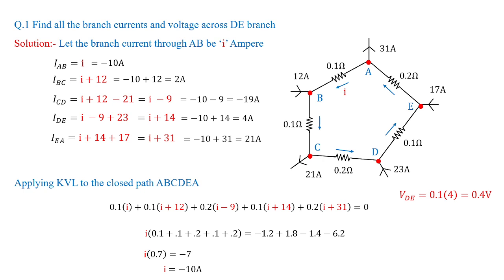In order to cross-check our result, you just apply KVL in the anti-clockwise direction and you have to get the sum of the voltages equivalent to 0. You can comment in the chat box whether you got the voltage drops in a loop equal to 0 or not.